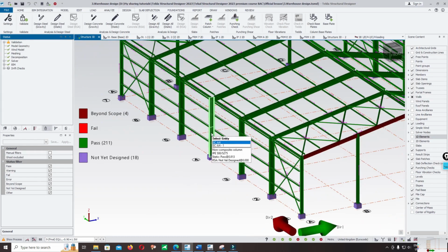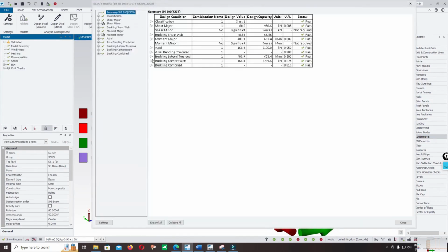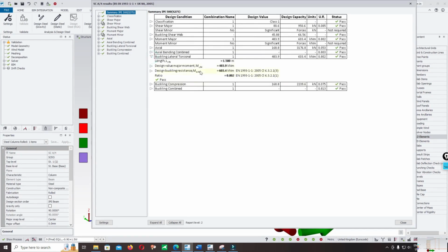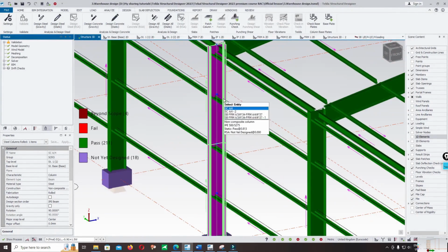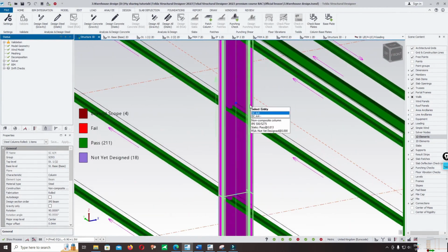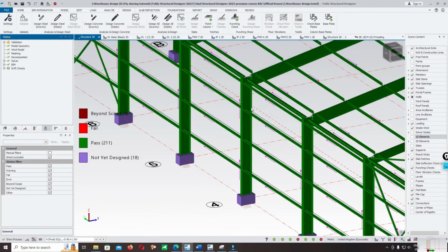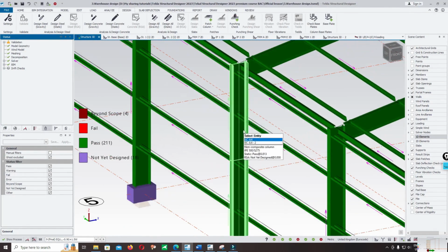Now check at the middle column by right click and check static and check for the lateral torsional buckling. The length LTB is equal to 1.5 meter. So we have to add the lateral torsional restraint at the intersection of the purlin with the bottom plane of the column. I will show you later how we can add the restraint to the purlin and to the column.